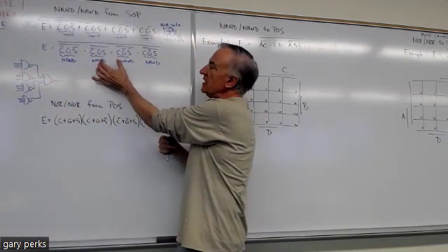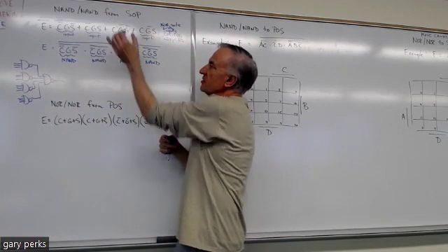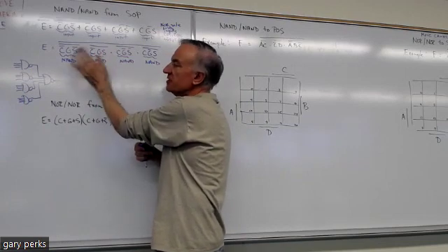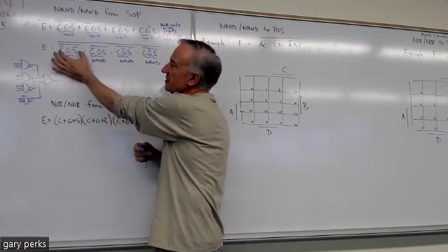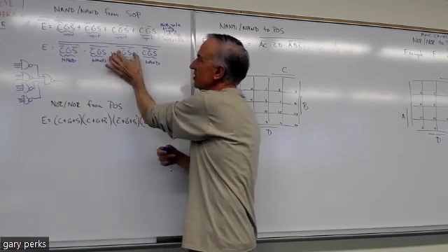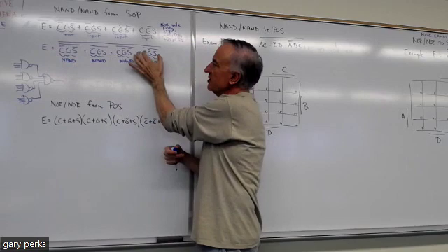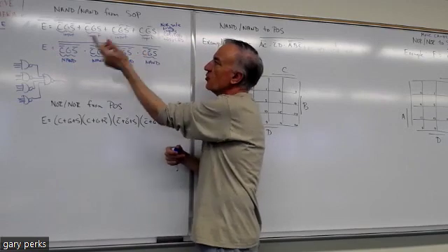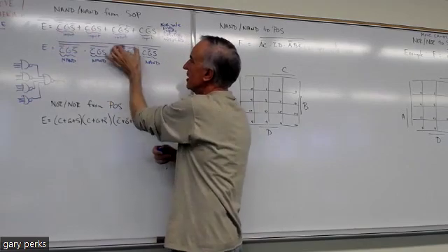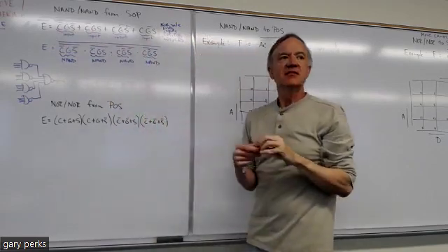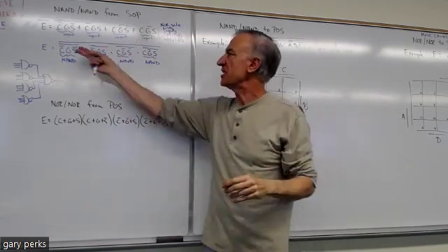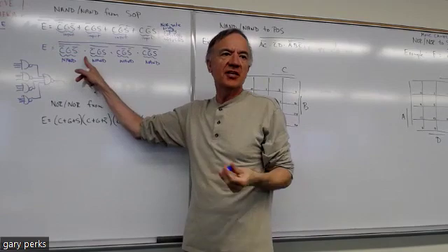To go from NAND to SOP, all you got to do is take the terms underneath the bars, right? So you take not C, G, not F, and not C, G, F, C, not G, not F, C, not G, F. Take those terms and just OR them together, right? See how that term ORed with that term, ORed with that term, ORed with that term. So to go from NAND to SOP, it's basically getting rid of the bars and just ORing all the terms together.